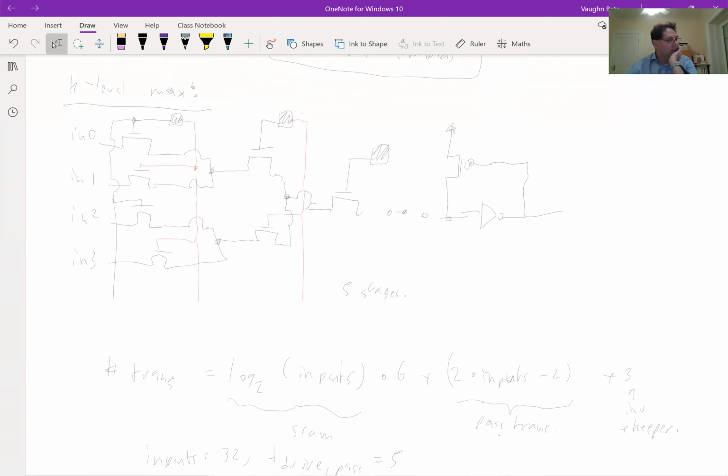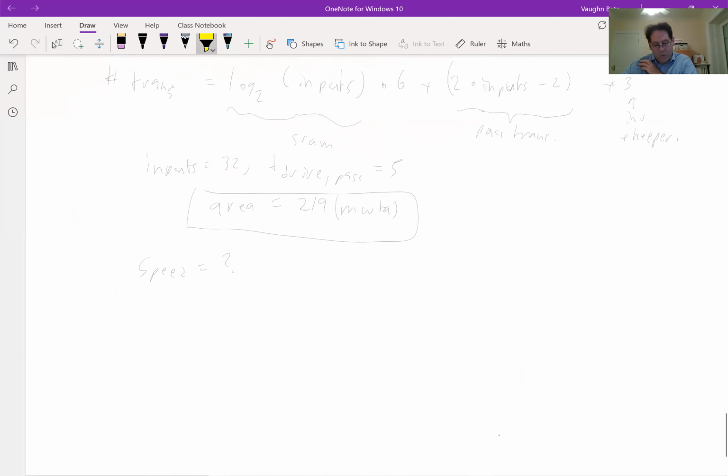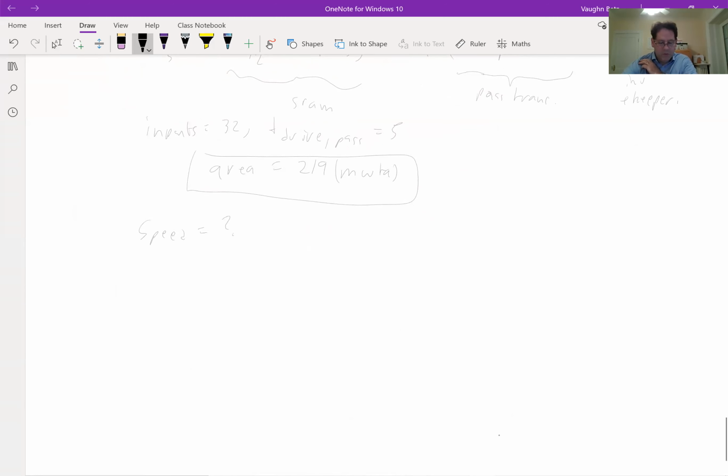Yeah, so it is slower. Because you've got more pass transistors in sequence, a reasonable model of this is you replace the transistors in your mind, or even in equations, by resistances, and then the delay is the capacitance that has to be discharged by every resistance. You just add all that up. So we've got 5 times as much resistance to this final capacitance here. It won't actually be 5 times slower, but it will be slower.